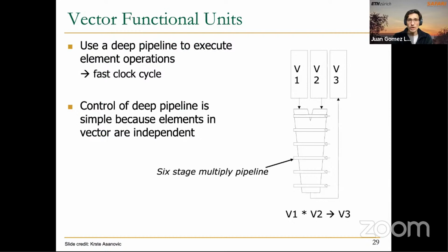But then we can talk more about the vector functional units, and this will also help clarify the idea. We said before we have a long vector, meaning we have multiple elements, and we are going to execute the same instruction on all these elements. This gives us the possibility to pipeline the execution. Pipelining the execution means that in the first cycle we start executing the instruction on element 0 in register 0.